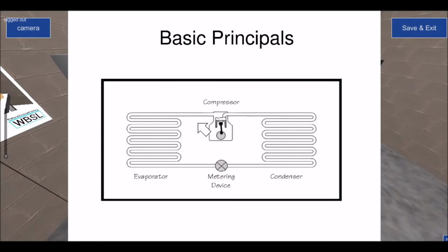So using a mechanical expansion device or metering device, say for example the thermostatic expansion valve, we set up a predetermined superheat value, and usually that's between 5 and 8 degrees of a difference. I'll explain that to you a little later on. And the reason for that, again, is because it takes a thermostatic or mechanical expansion valve 15 to 20 minutes to react. So that's why we need to have that safety margin built in.